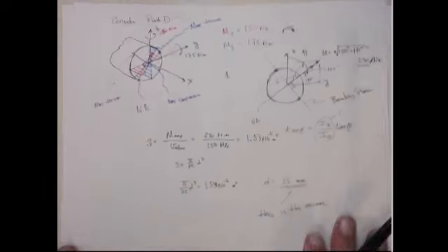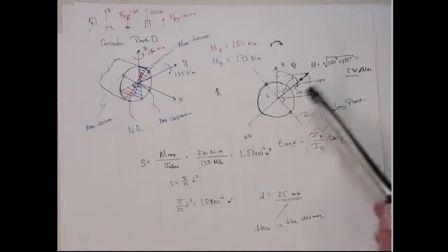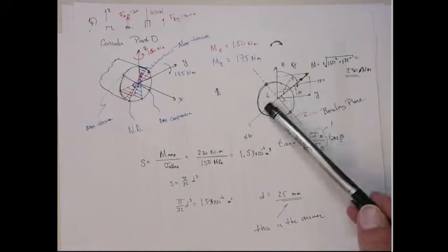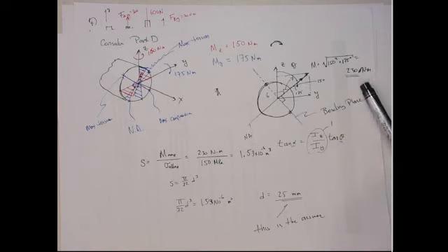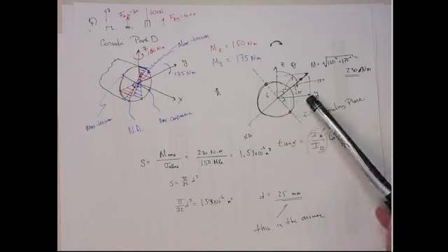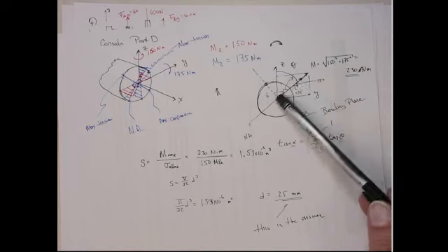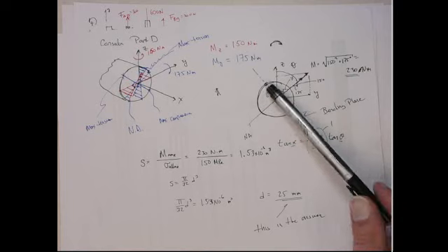Now doing the same thing at point D. Now at point D we have both stresses, all right? So we can figure out the total bending moment, the net vector, right? The My and the Mz are the components, so that gives us a total bending moment of 230 newton meters at this orientation where you're going 7 this way and 6 this way, right? That's the direction. Okay, so perpendicular to that is the bending plane.